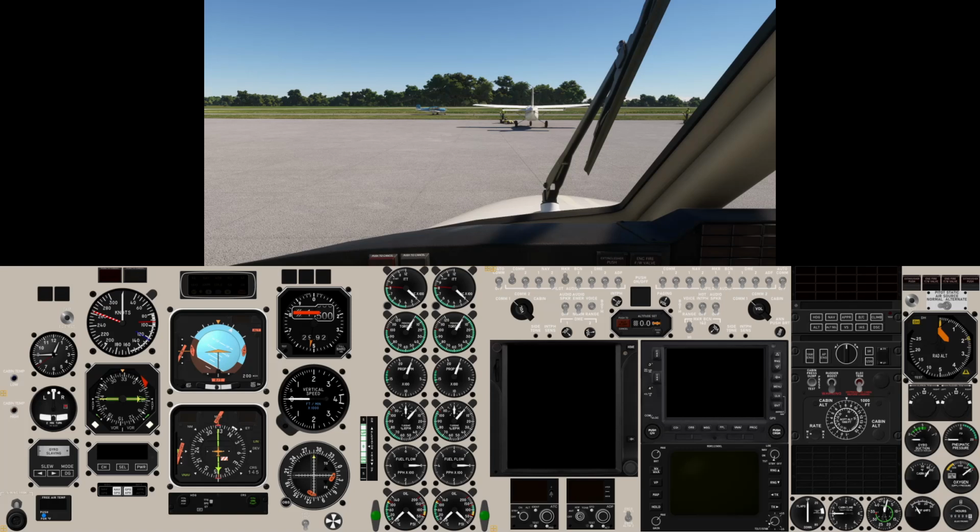There's a pitot static at the very top there, and then above those are the engine fire annunciations and switches. And then in the central area there, the master warning and caution system is split into two annunciator panels. So all the warnings, all the red ones, are on one panel up the top of the glare shield, and that's the top panel you see in that little stack there.